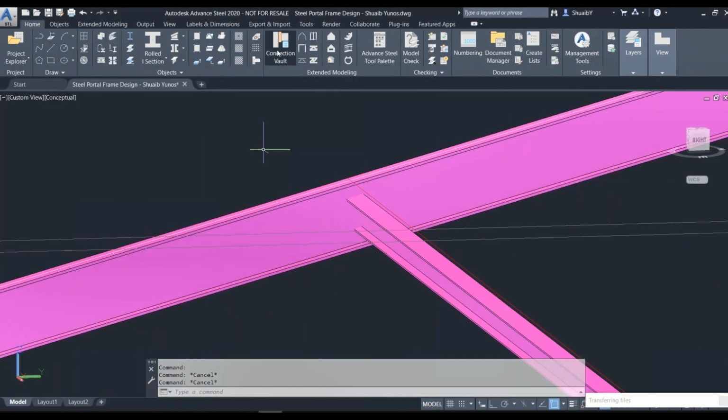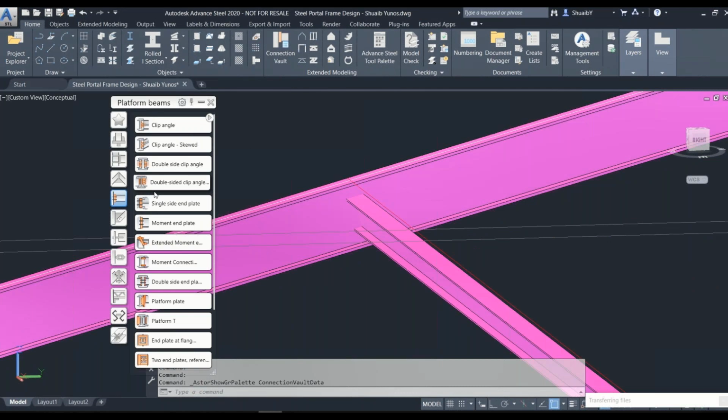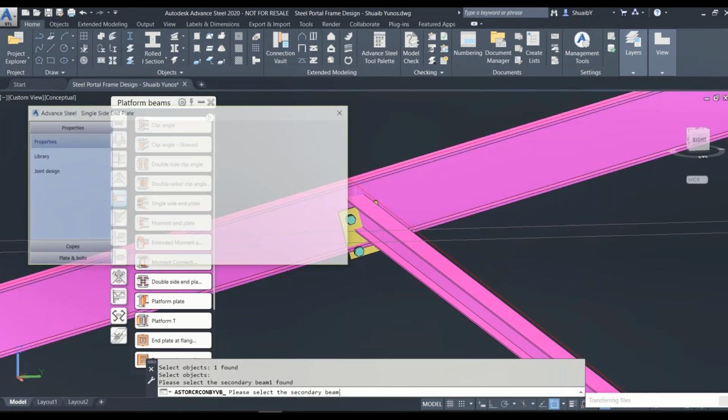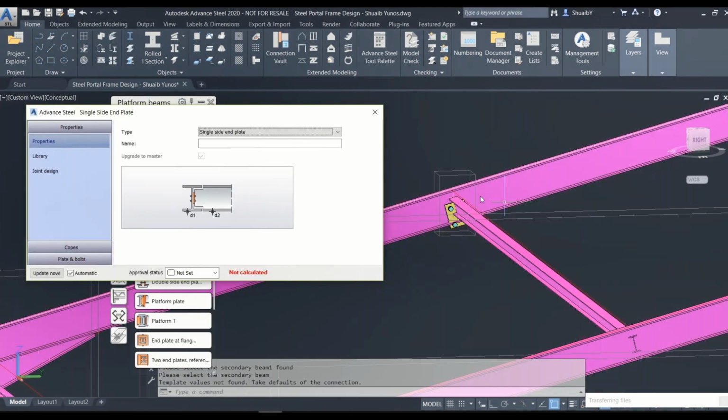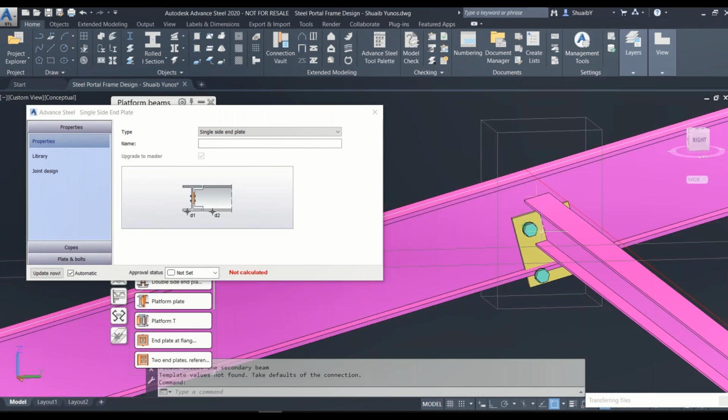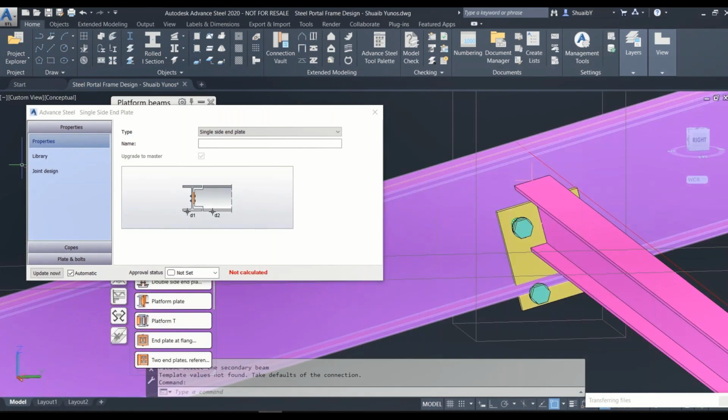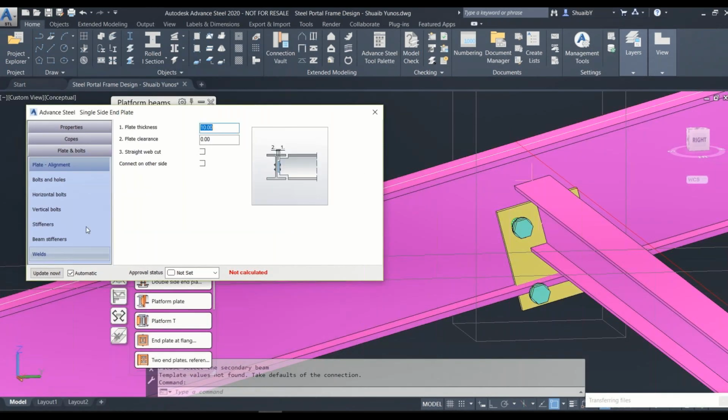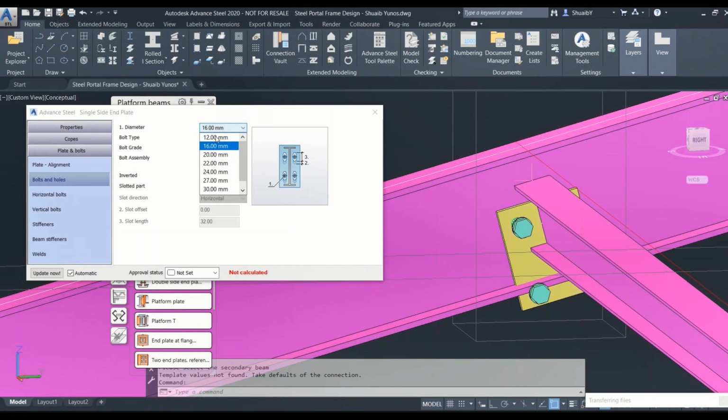So as you can see, we've got the angle correctly. Now I'm going to attach another single plate. So if you didn't catch the first one, let's go through this again. You can see that there's a gray box along or around the connection. Those are called connection boxes. And if you double click on them or right click and say advanced joint properties, you can edit it.